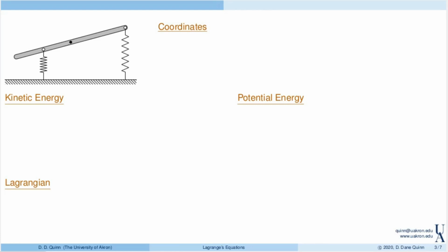So the first thing we do is coordinates, right? We want to identify the way that we're going to describe the configuration and the forces that act on the system. So as I mentioned, it's a 2-degree of freedom system. We'll start off and define directions I and J. We'll look at the linearized motion for this problem. So we'll assume that the angles are small, and in particular that implies that sine of theta is approximately theta, and cosine of theta is approximately 1.